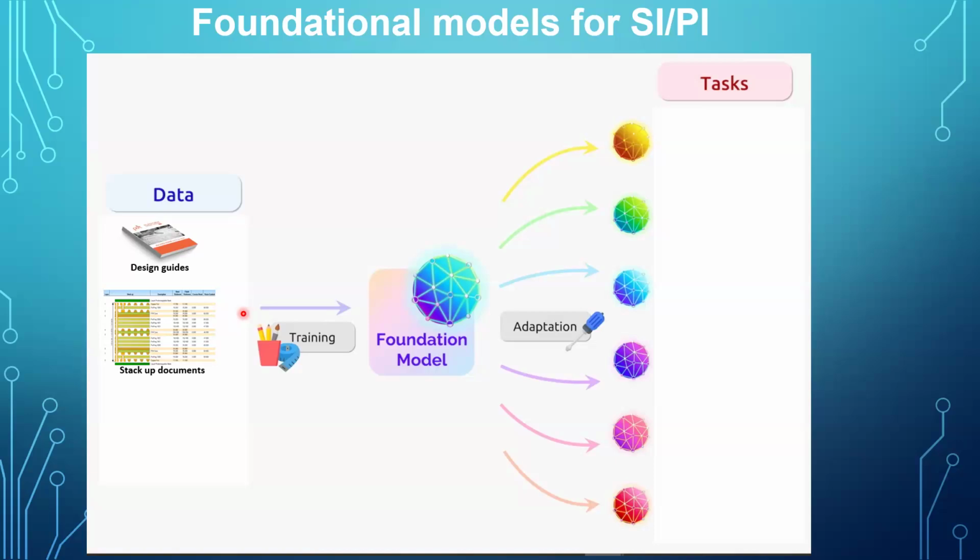For example, we have our own stack-up and documents on how we implement it: geometries, transmission lines, spacings, all the rules. Our manufacturing partners, the ODMs, also give us design rules, the DFM spec. All of these are very well documented with our knowledge.